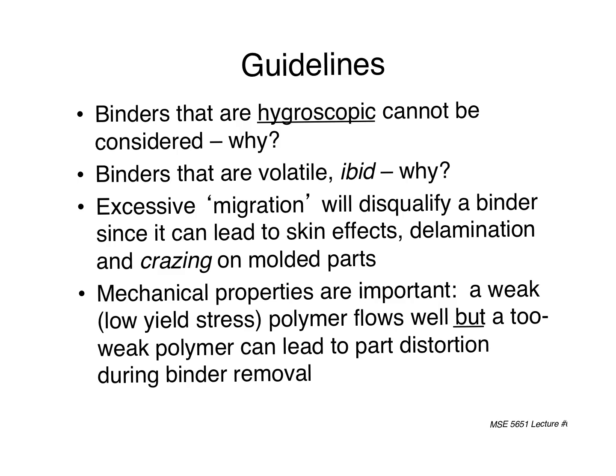And so we don't want to have that in this context because of why? Why would that be a problem for us in terms of our injection molded part? It sucked water out of the air. So when we take that part and put it into a furnace, the water's got to come back out, right? As part of that heating up process. And if there's enough of it, it can blow the thing apart, which is unlikely. But still, you've got something that's taking up space and needs to be removed and can compromise the strength of your part. All right, it becomes a very delicate balance.